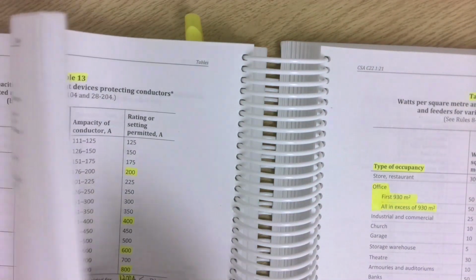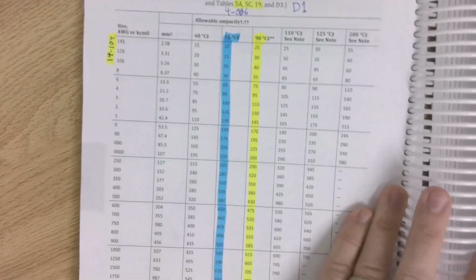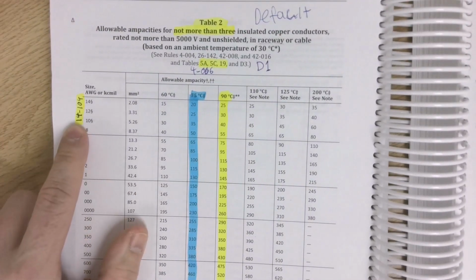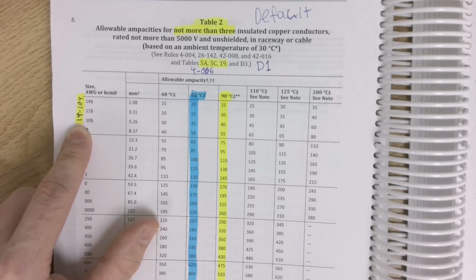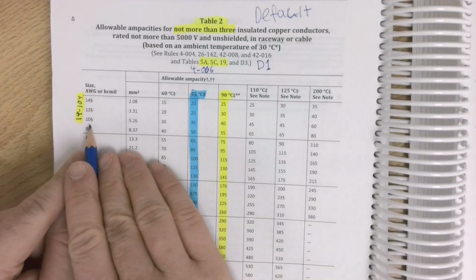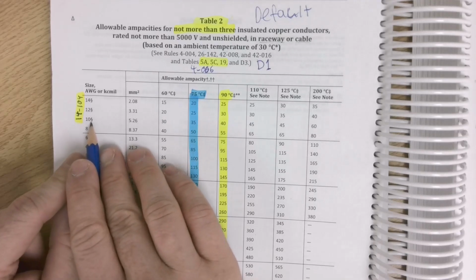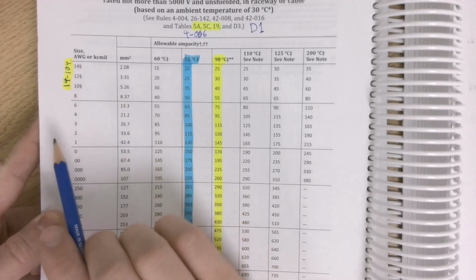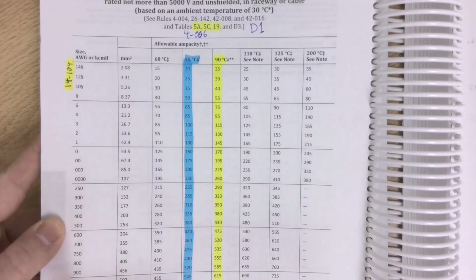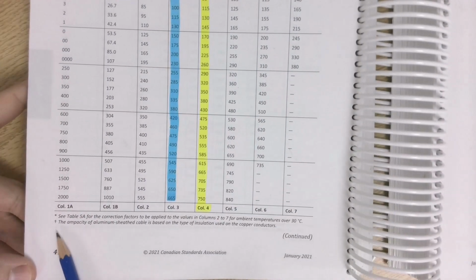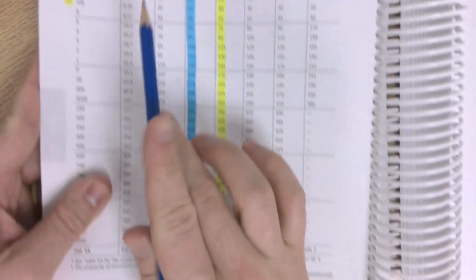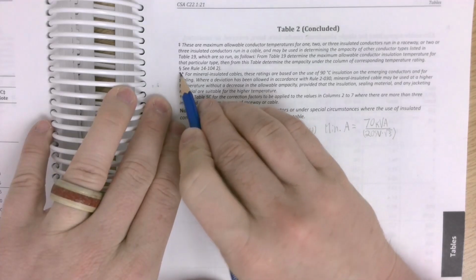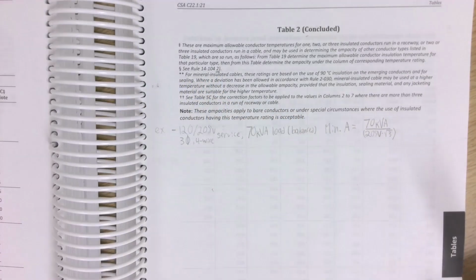Because if we go back to where we got that wire from, you may have already spoiled it for yourself because I wrote 14-104 right here. And the reason I know that it's 14-104 is these little squiggly S with a circle in the middle things beside 14 gauge, 12 gauge, and 10 gauge. Whenever you see something like that, like an asterisk or these little crosses beside things in a table, it's directing you to look at notes associated with the table. And so our little S squiggle thing, I have no idea what that actually is, is going to send us over to C rule 14-104 2. Okay, well, we looked at 1. Why is 2 so special?